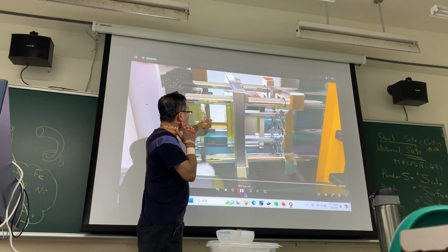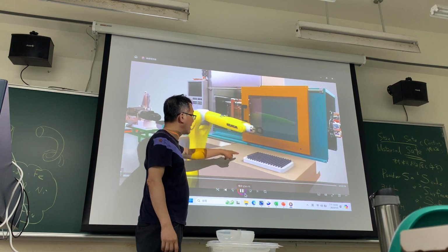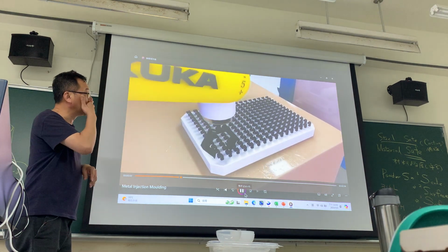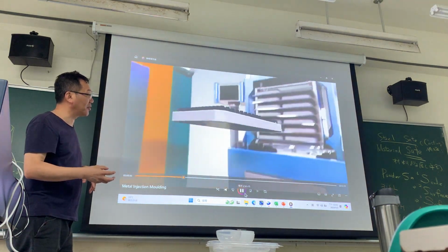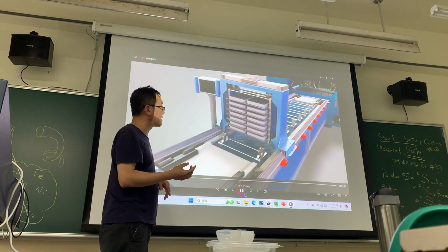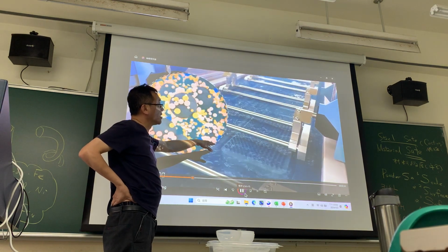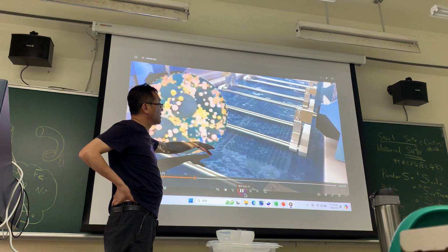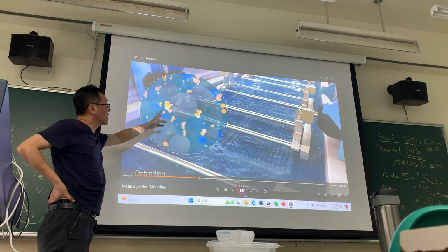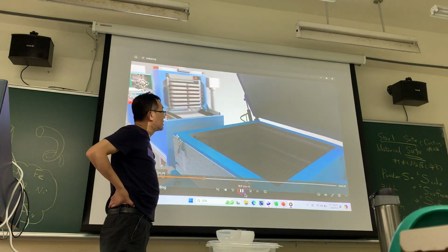This is a mold. The mold has many cavities, and then this is the green part. Green part means metal and binder mixed together. Before sintering, we should remove the binder. We call this debinding. This way is solvent debinding, and now we use catalytic debinding. It's different. This is a chemical way, and this is a physical way. The wax and the polymer will go outside and leave the metal powder.